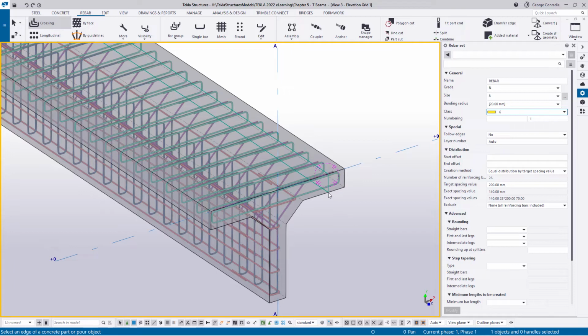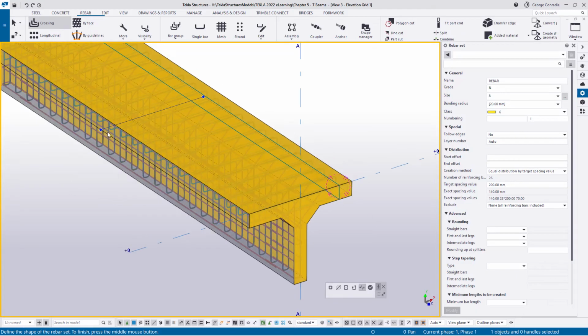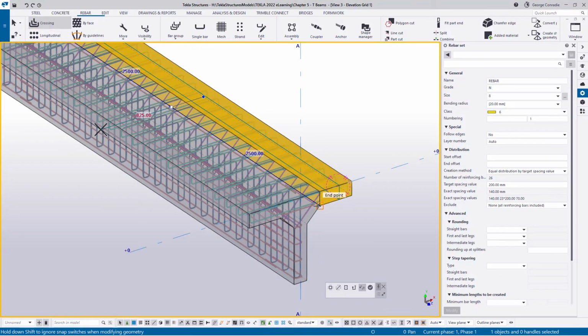If we hover over this, Tekla is going to give us the right bar, but the faces are going to be a bit of a mess. If I just enable our face, it's going to try and fit the bars through all these faces, so you can get all kinds of different bars in here. So that is not an option. Well, what is an option is you could again drag this down to that point and say, okay, that's correct, and then pull these faces all the way to that end. But that becomes also hard work.